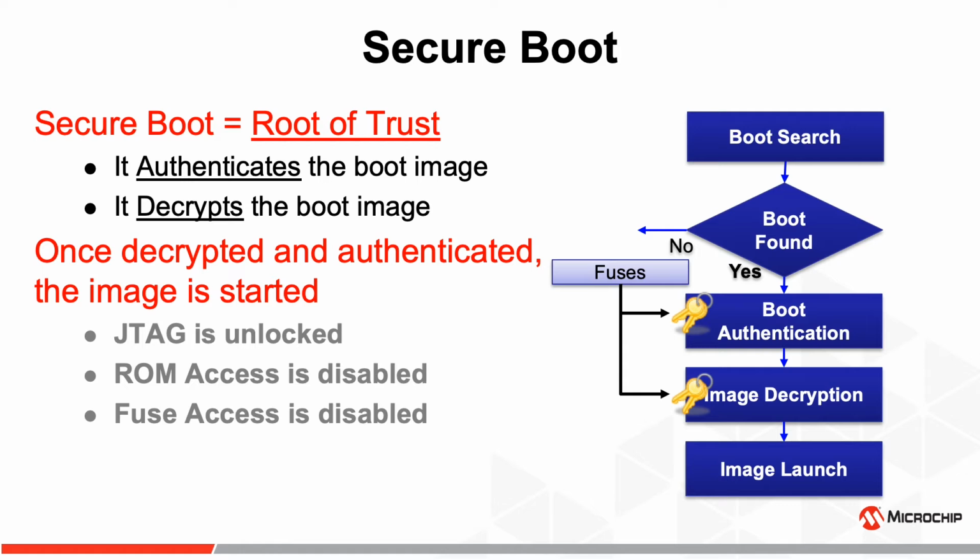Secure boot uses a number of functions in the device, like the boot ROM code, which is executed by the processor, which is the initial process of the starting of the boot. The processor looks for a valid image. If it finds an authenticated image, it will continue to decrypt into internal memory. If no image is found, it will go into a provisioning loop, looking for the provisioning tool.